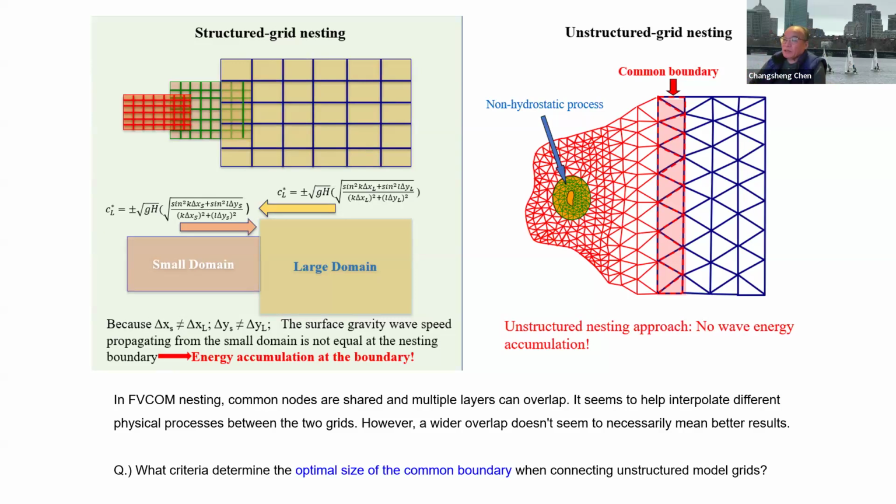So you have to consider two cases, depending on the case study. For example, if you study tide-driven or wind-driven motion, your boundary can be close to the coast. It does not really matter because you do one-way nesting, with the larger domain model driving the small domain model. So you want to make sure reflection from the small domain to the big domain is small, but you do one-way nesting.